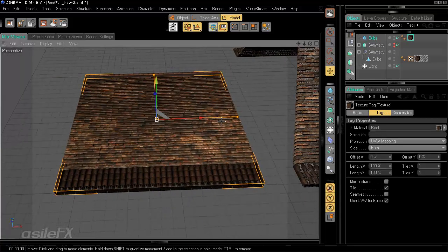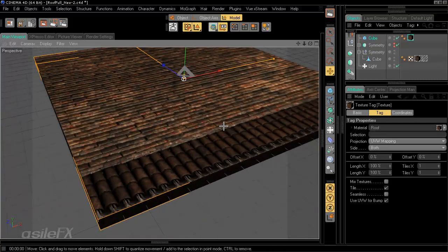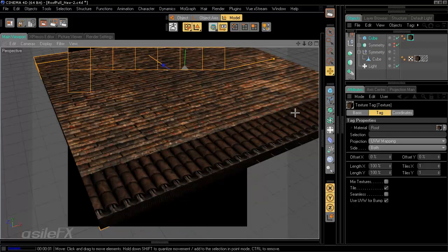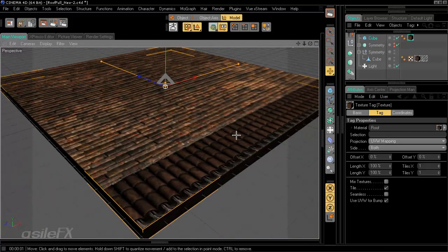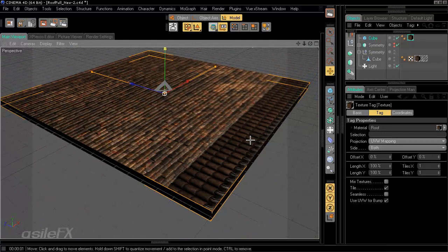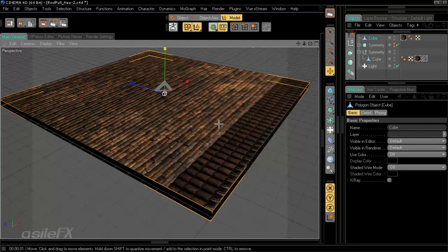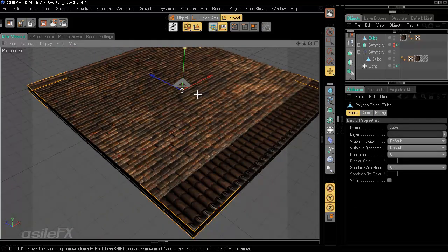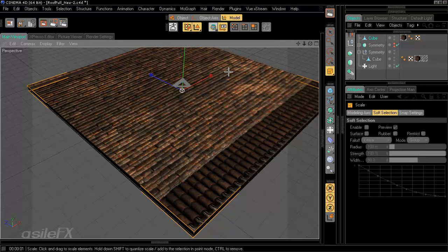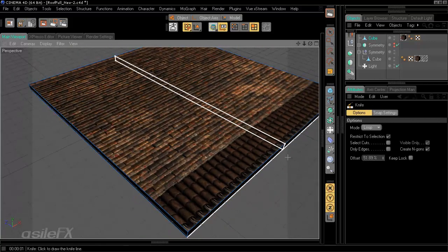And you can see after I set up the normal maps and all of that, how it is applied. What I then did was made the object editable. C, so make editable, and bake to polygons. Just going to scale this down just a little. And then K on the keyboard to pull up the knife tool.